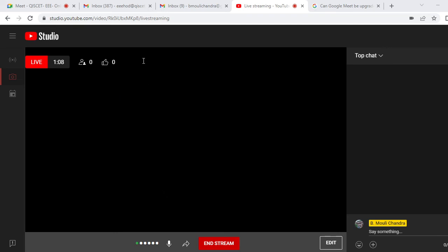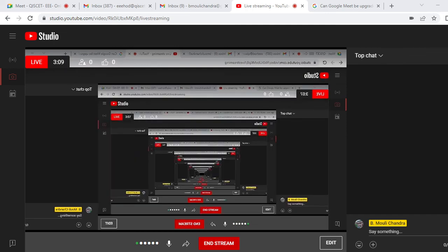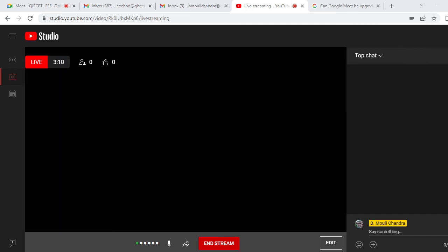Here one network is there, and that network is converted into a graph. These are the different nodes, buses or nodes, given by dot points. And we are having the lines, and each line is given by an edge. So here a three-bus network is represented by three nodes and three edges. Now, if you want to make it radial, we should disconnect any one of the lines such that it is not in a mesh condition. There will be no loop.